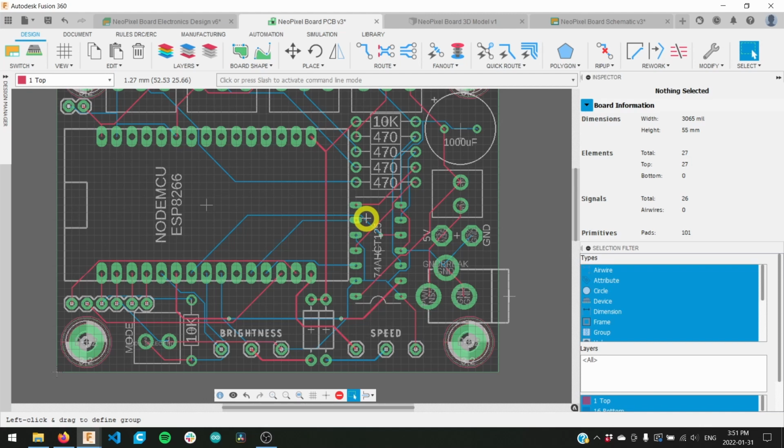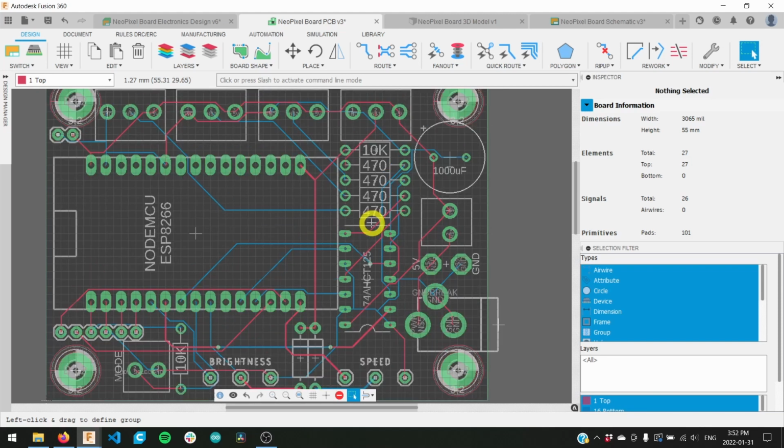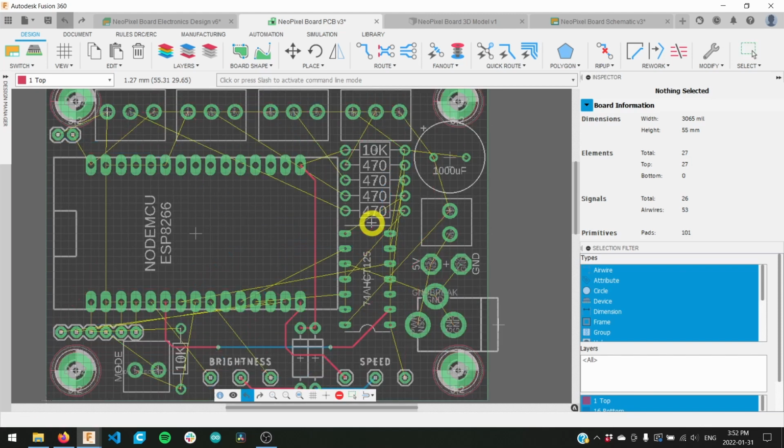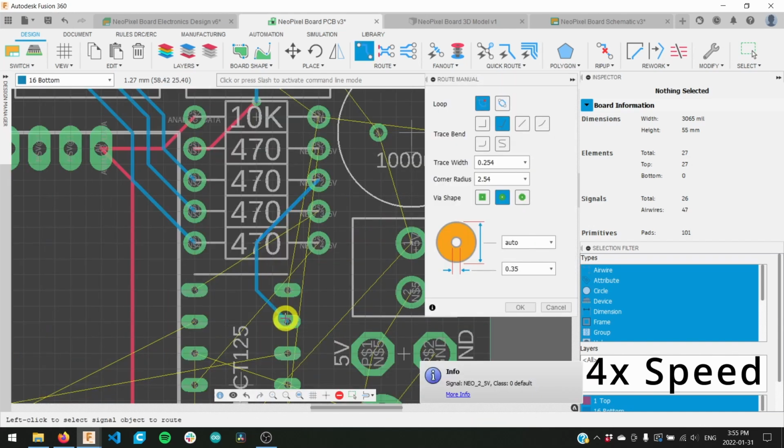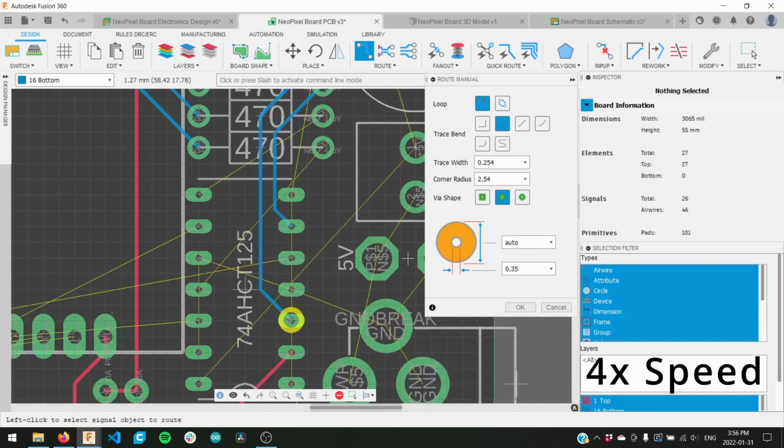But the general consensus amongst the electrical engineering community is that manually laying traces is almost always superior compared to using the Autorouter because of the reasons I mentioned regarding component placement, complexity, and overall aesthetics. So I'll go ahead and undo what the Autorouter just did for me and continue manually placing the traces. To be honest, I actually find laying the traces manually to be the best part of designing a PCB.